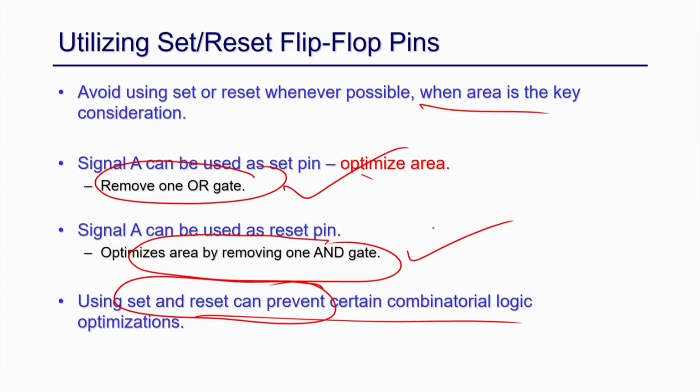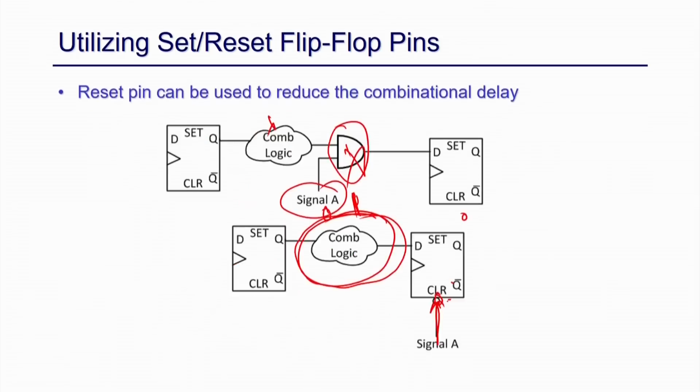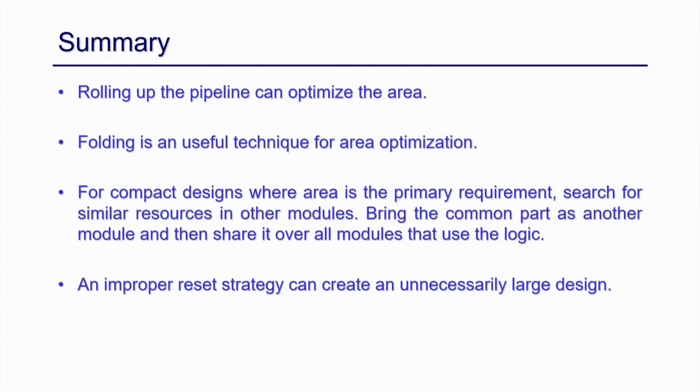So, the idea is that when you are designing something, you should always try to keep your set and reset pin unused, so that this kind of combinational optimization can be done by the synthesis tool, specifically for FPGA targets. Okay. So, we will just conclude with this.